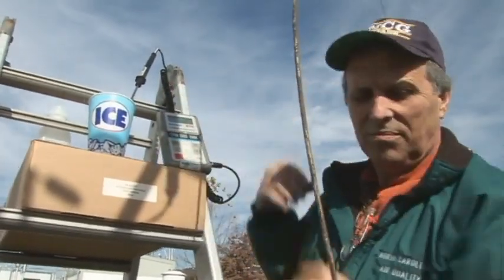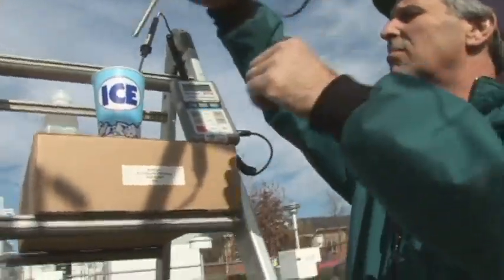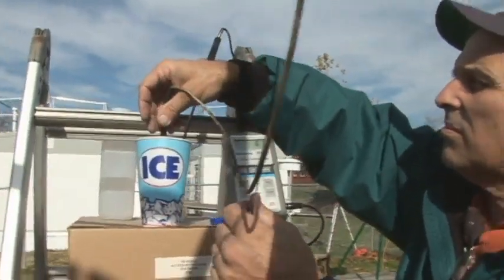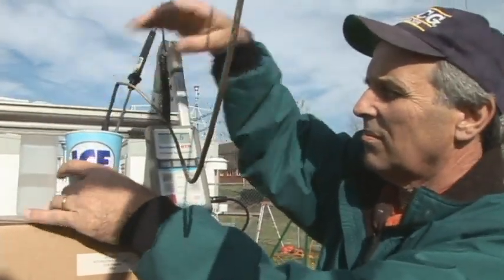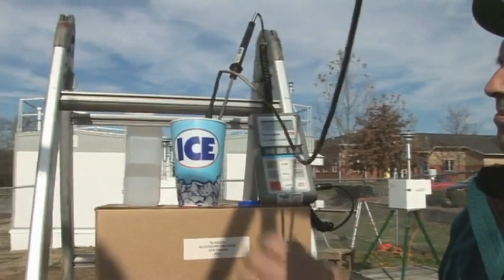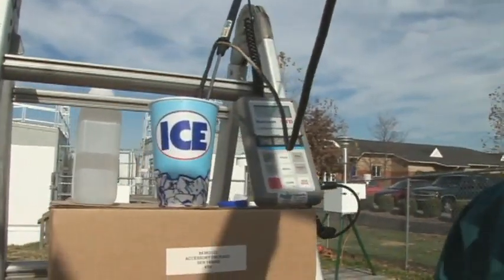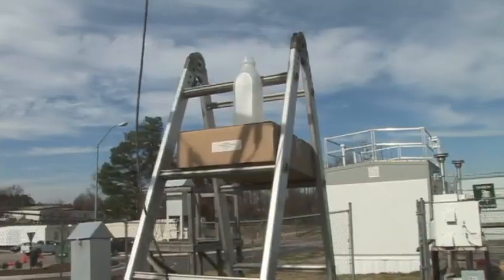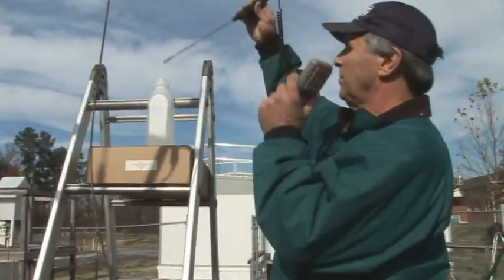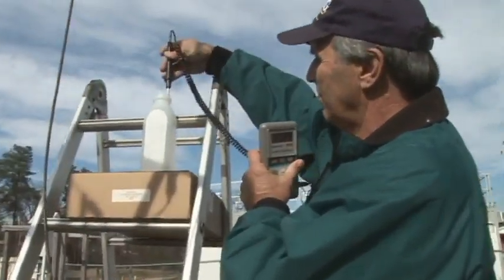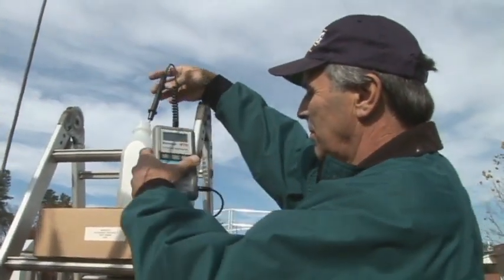A helpful hint here is to tape or rubber band the calibration thermometer and the temperature probe together so they measure the water in the same area of the slurry. It is recommended that the outside technician stir the probe and thermometer. Now that the first calibration point has been recorded, the outside technician must now prepare for the second calibration point.